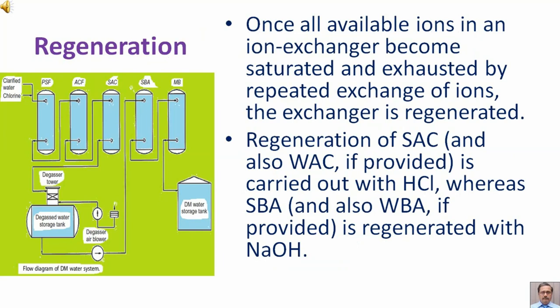Regeneration of SAC and also WAC, if provided, is carried out with hydrochloric acid, whereas SBA and also WBA, if provided, is regenerated with sodium hydroxide.